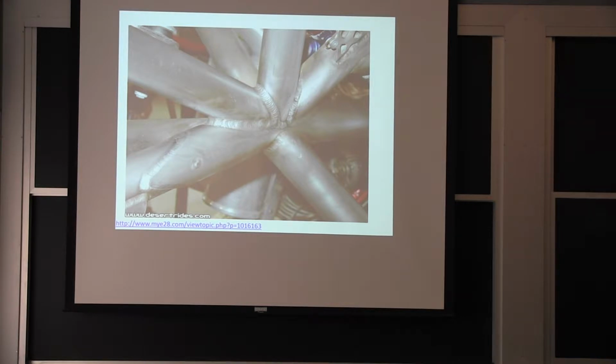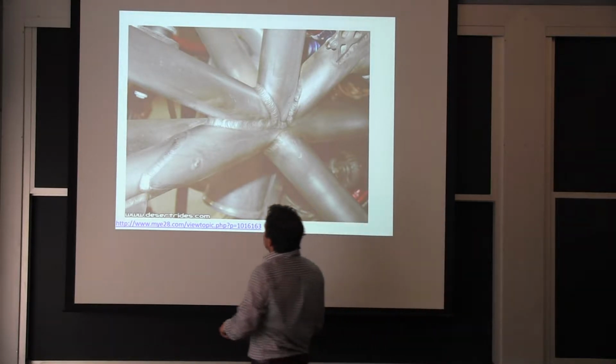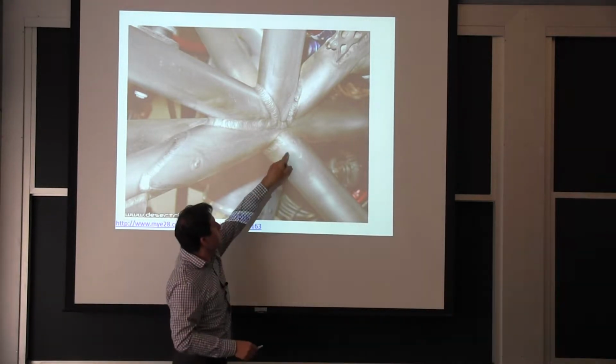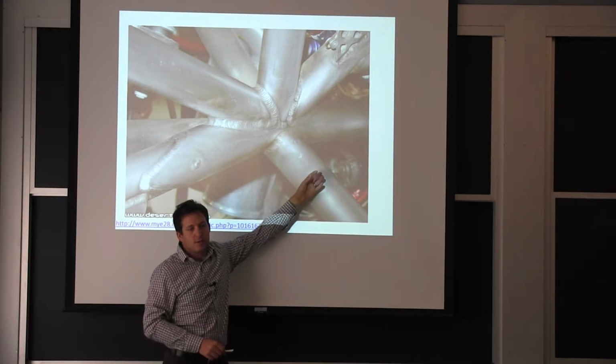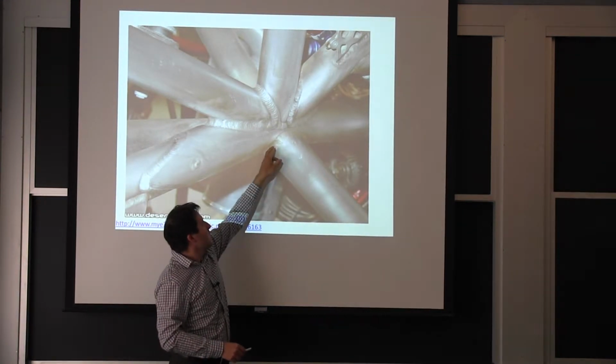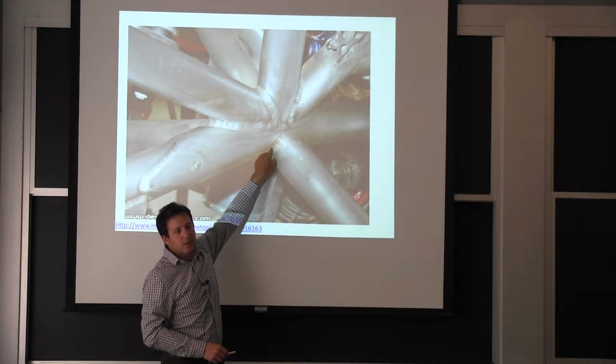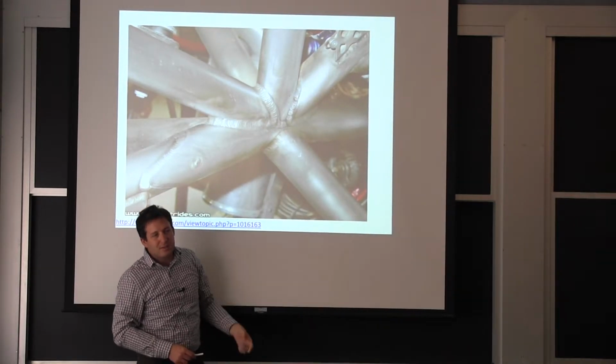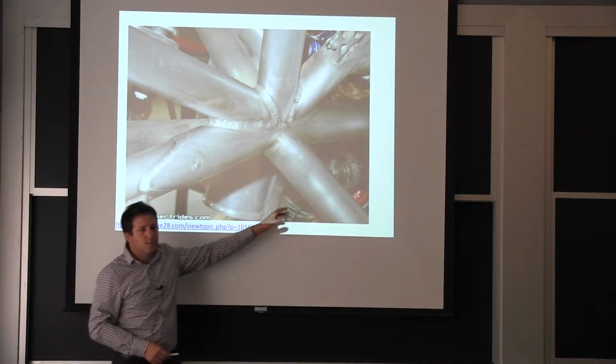Not without any issues. And by that I mean welding aluminum changes all that heat treatment, everything that we talked about, quenching and aging. And therefore, a lot of times you try to avoid these types of joints. I'm sure you've seen them on bicycles. What happens with this joint is, say this member is loaded in tension, compression, or even worse, there's a little bit of bending on it. You get a lot of stresses here at the toe of the weld, and that's an area where the material is a lot softer than the tube itself.